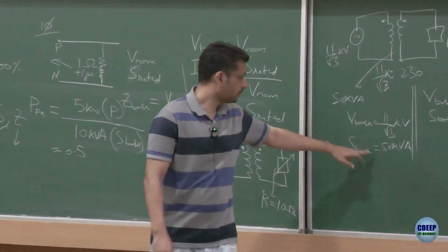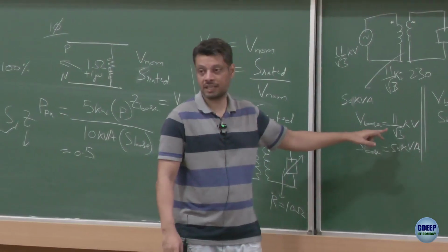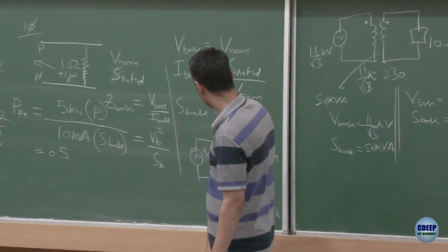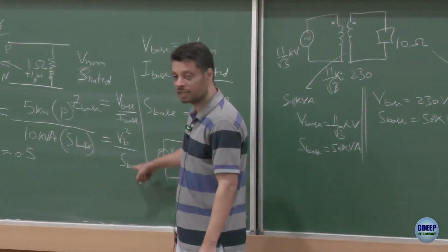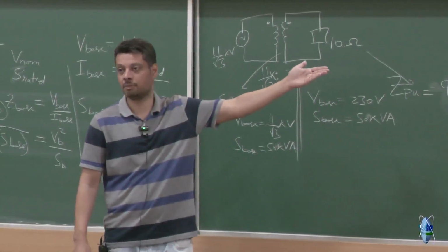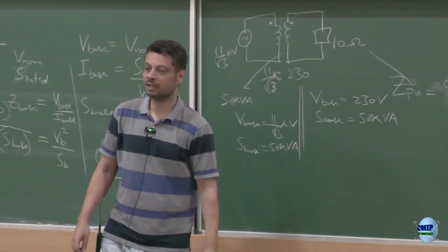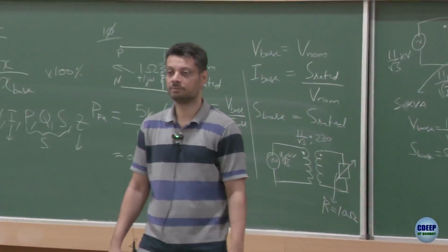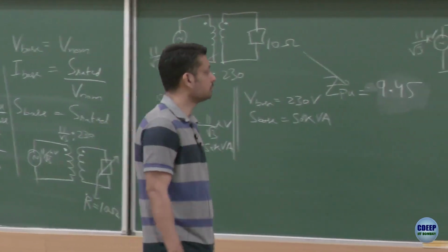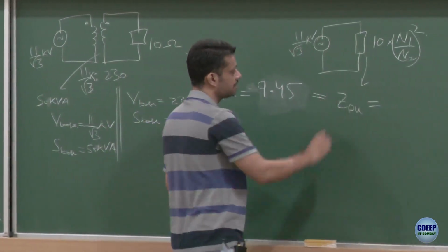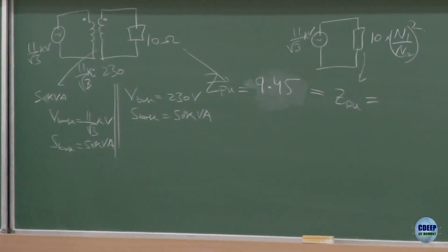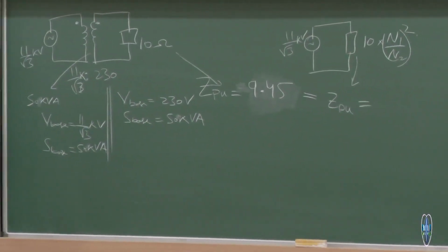You know the power, 50 kVA, you know the voltage base, Z base is equal to V square by S base. So calculate Z base, then divide that actual impedance by Z base. You will get the per unit value, right? You should get the same value, right? And that's how we have defined the base, and that's how we have defined the turns ratio.